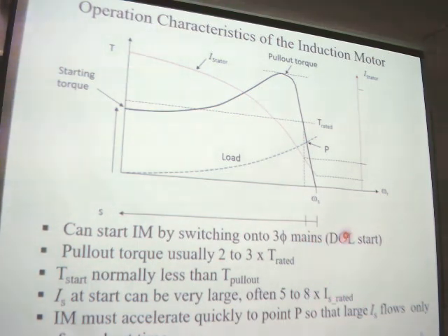But if we use this method, we'll see the stator current will be very large. When we start an induction motor with DOL start, direct online, the current will be 5 to 8, or sometimes 10 times the rated current.